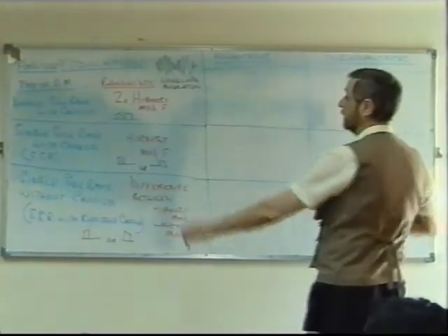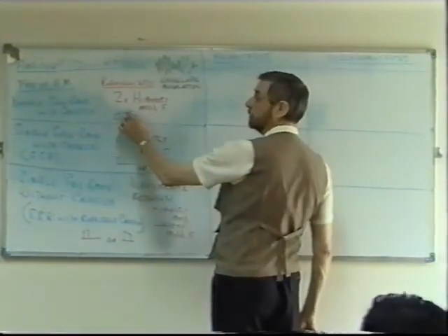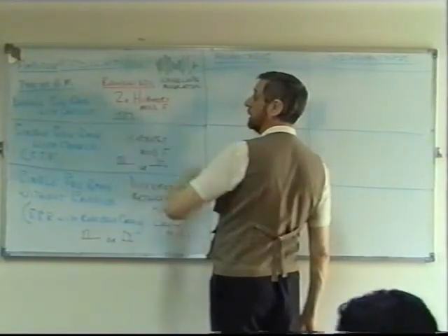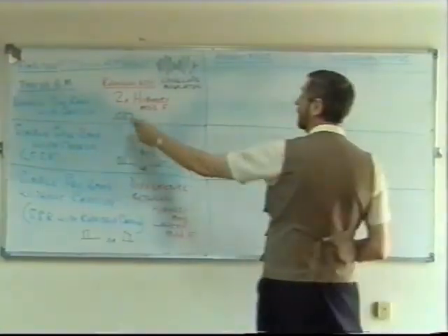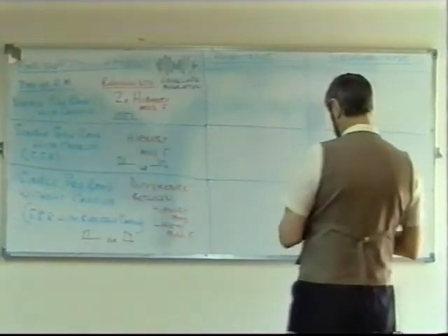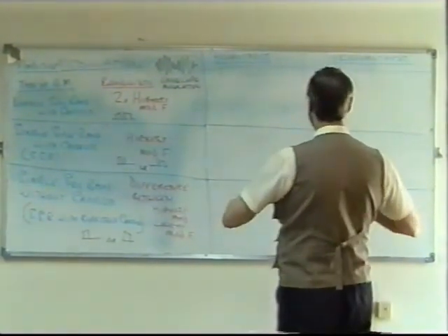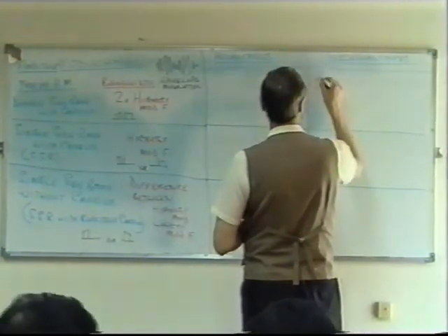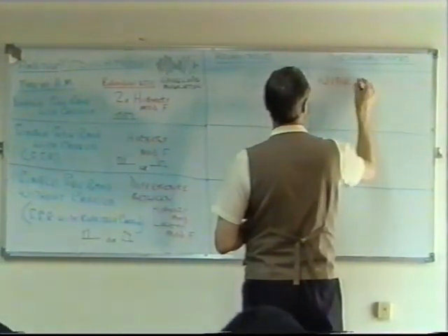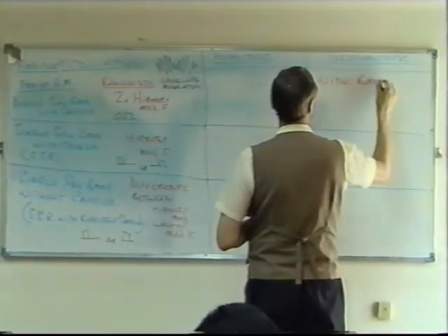That's true. Not only are we wasting bandwidth, because we're transmitting 2 sidebands when we only really need 1 for the information, but it's not efficient power-wise either. But in fact, the main disadvantage that I'd like you to remember is wide bandwidth. I'll just put that down here.